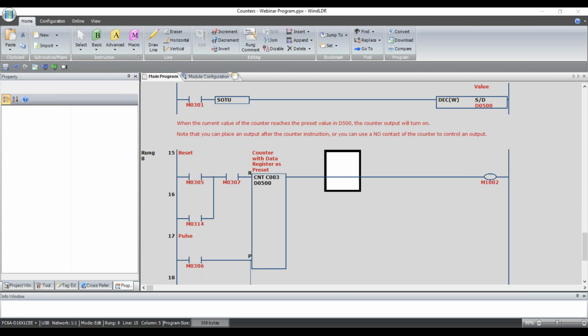Let's see, which FC6A digital input card is suitable for 100 pulses per unit at 12 units per minute? Do the points coming with the FC6A as standard work? I think the TTL will work for 0 to 24. Okay, so let me do the second question first. All of the inputs on the PLCs are 24-volt DC inputs. So when there's 0 voltage going to them, they're off. When there's 24 volts going to them, they're on. And again, these are the digital inputs.